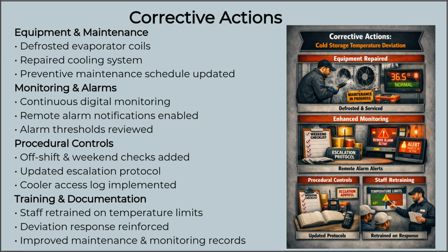2. Monitoring and alarms. The cooler was upgraded with continuous digital temperature monitoring. Remote alarm notifications were activated so QA and maintenance receive alerts instantly. Alarm thresholds and response times were reviewed to ensure early detection.